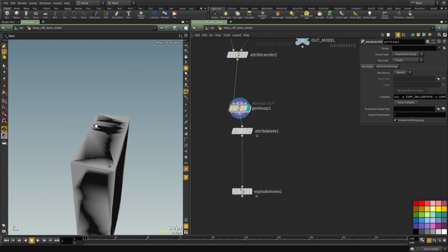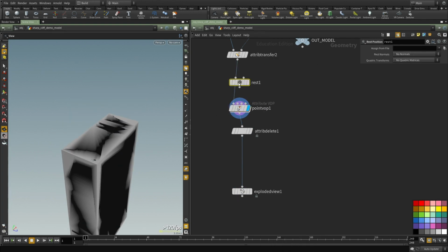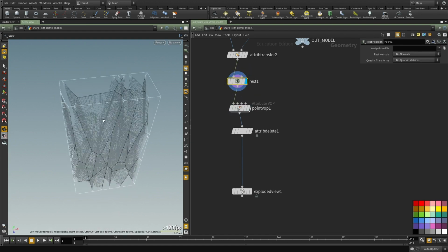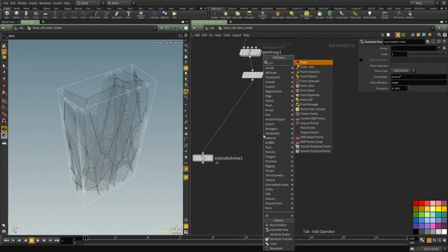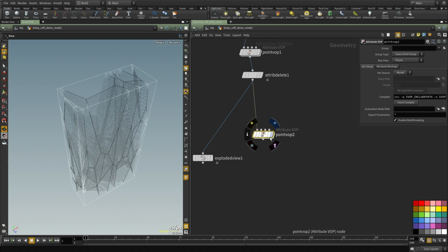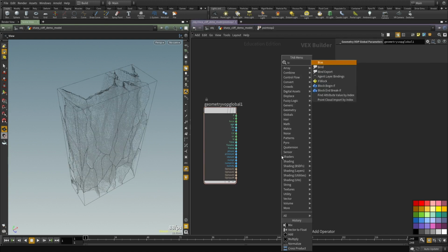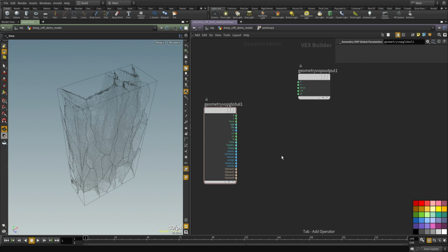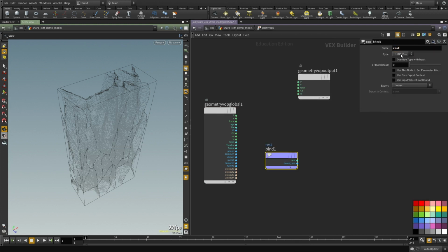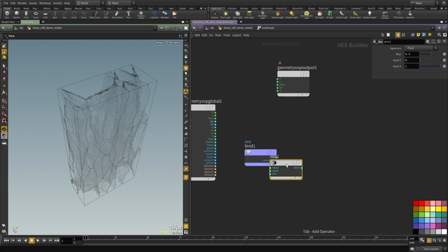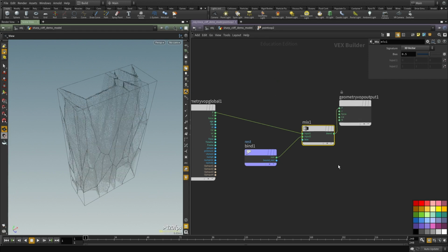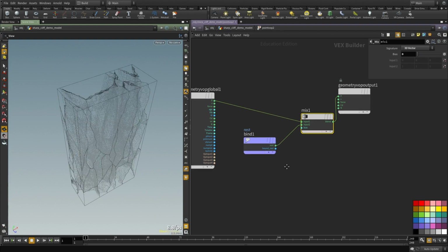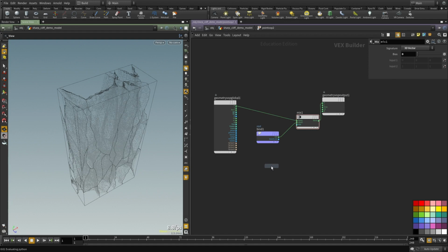So what I'm going to do is use that also to blend in all of this. I'm going to create a rest attribute to copy the position of the points at their original state, and then I'm going to create a new point VOP. I don't want to do everything in one place, so let's create a new point VOP, and let's bind import the rest. Okay, and then mix between the new position and the rest using that depth mask. Cool. So now we have this slider. This is the original. This is the deformed, and I want to import the depth mask and use that.